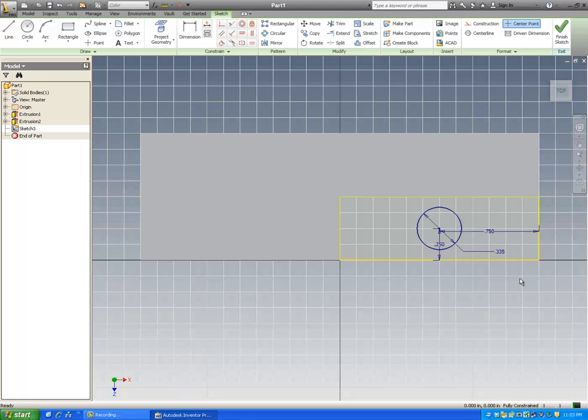0.25. So okay, we're 3/4 over, we're a quarter up, and I would advise you on your models to make all of your posts and your holes the same dimension. Well, actually, I would make the holes, let's say, quarter-inch posts. Okay, so I would make, and we're going to cut this into a hole. I would either make the posts or the holes about 20 thousandths oversized or undersized, depending on how you're looking at that. So I'll show you that in a minute.